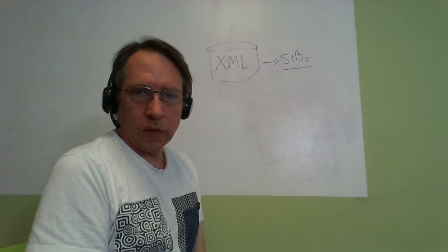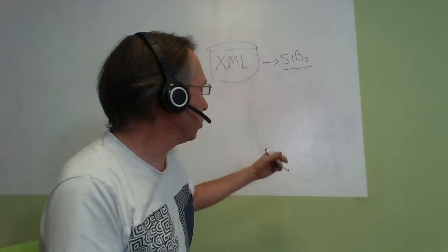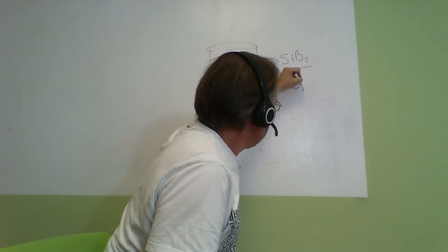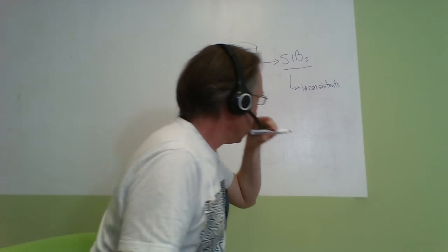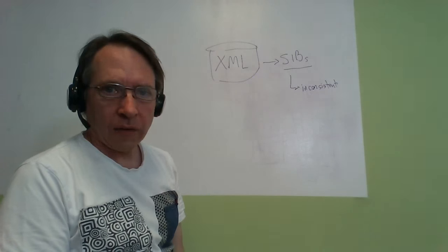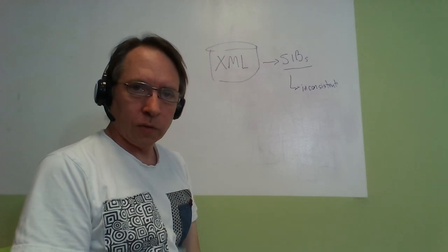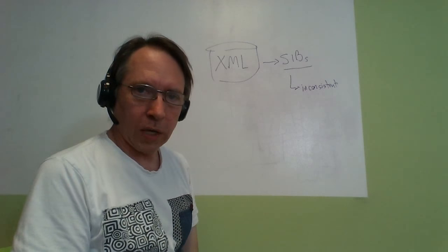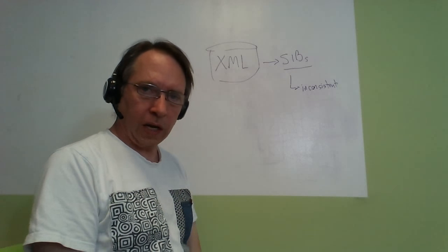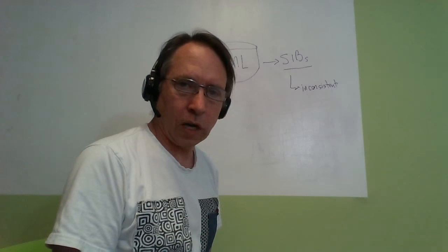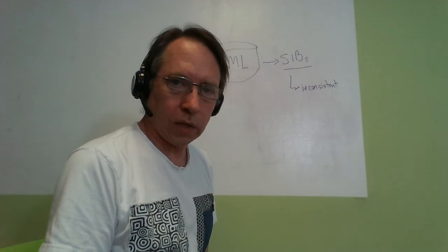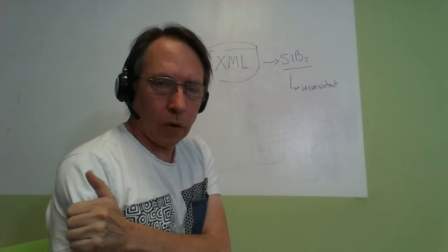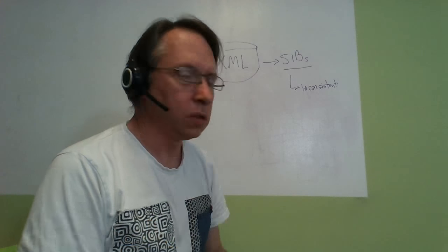So, things that we have seen customers do with SIBs that they found useful. One is to do inconsistent SIBs, which means SIBs that advertise services that are different from what the cell actually does. So the cell will basically tell the mobile device, hey, this is the service that I offer, and this is how I'm going to treat you. But then when the device connects, it behaves differently than what the device would have expected. And this is a useful type of test for interoperability testing and also for security testing.